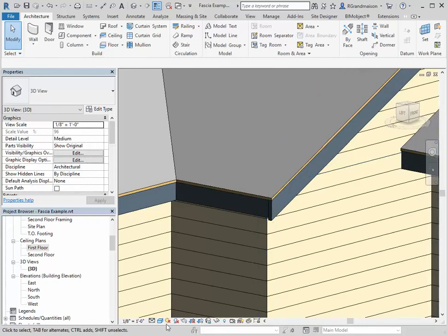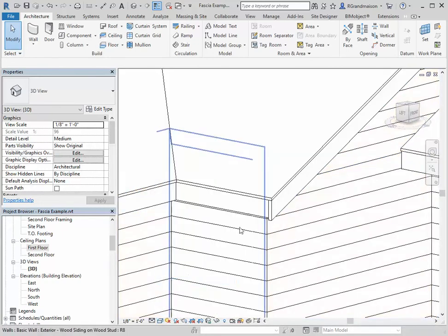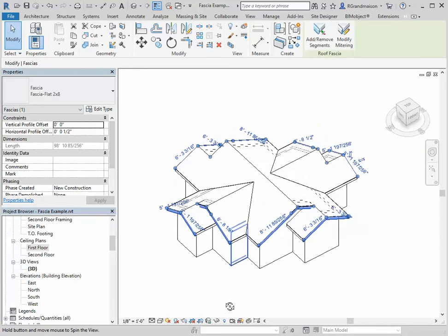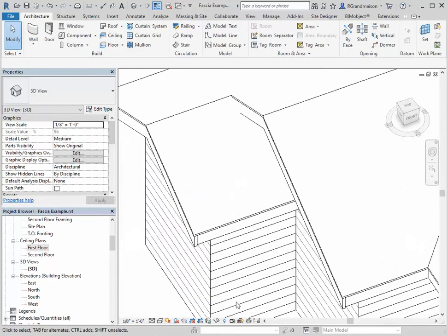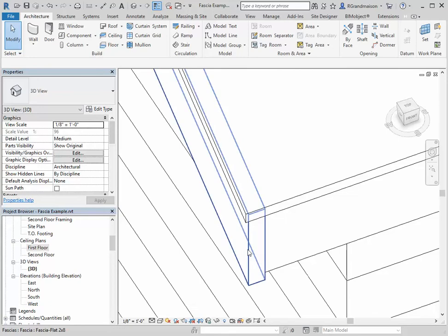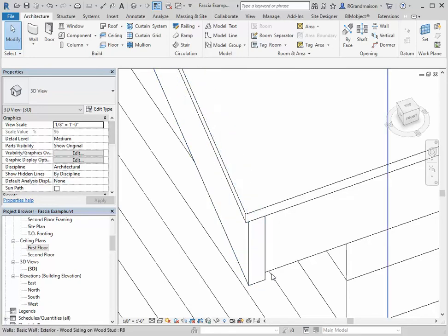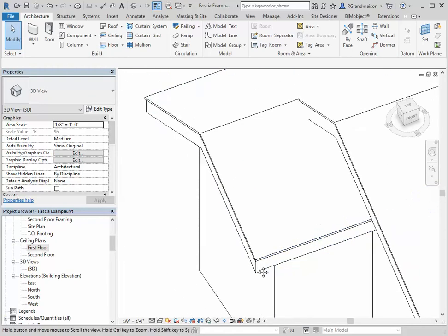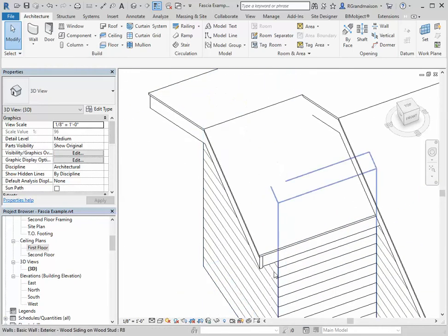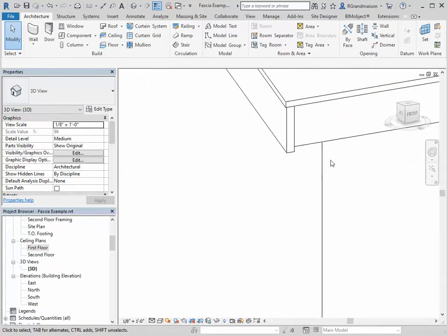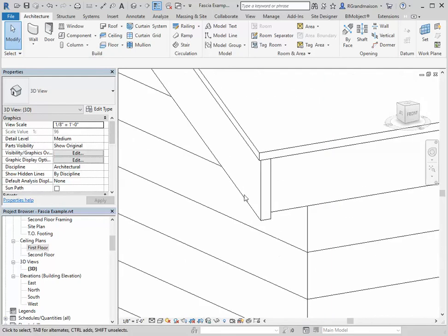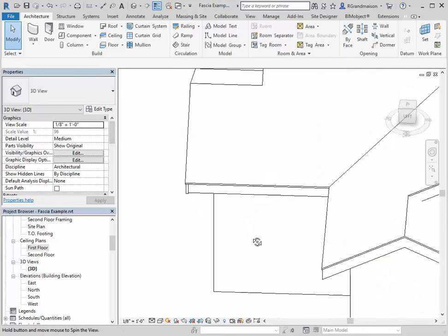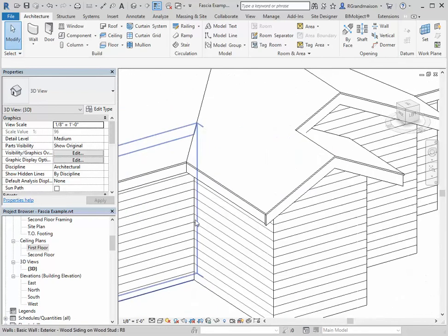One of the benefits to having the rakes all as one fascia component is I can do this with one void cut. So what I'm going to do here is I'll cut the bottoms of these tails a little bit everywhere, just so that they're flush to the underside of this. Let's say for some reason that's the way I wanted that particular detail to occur. But in reality, this is a very common way you'll see a rafter and an eave meet. They don't always trim the bottom side of this on buildings. So what I'm going to do here is show you a way to remedy that.